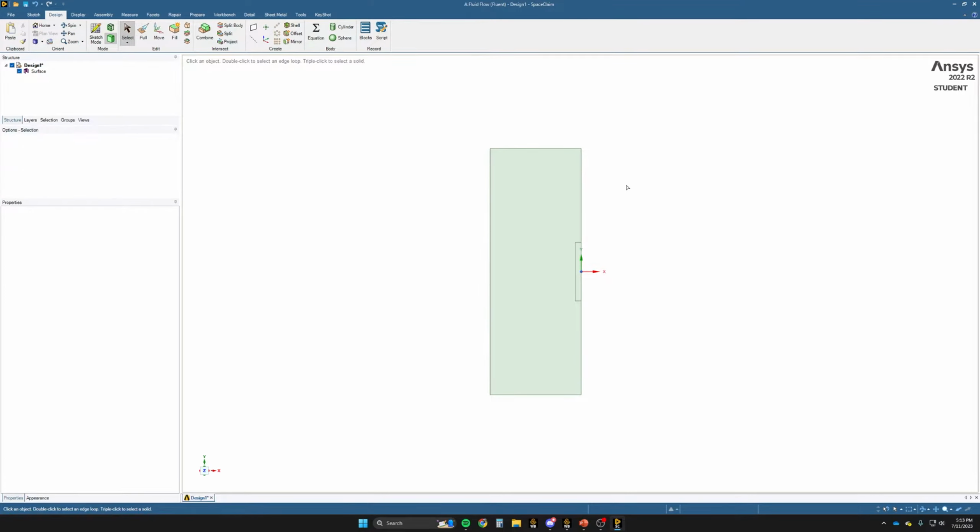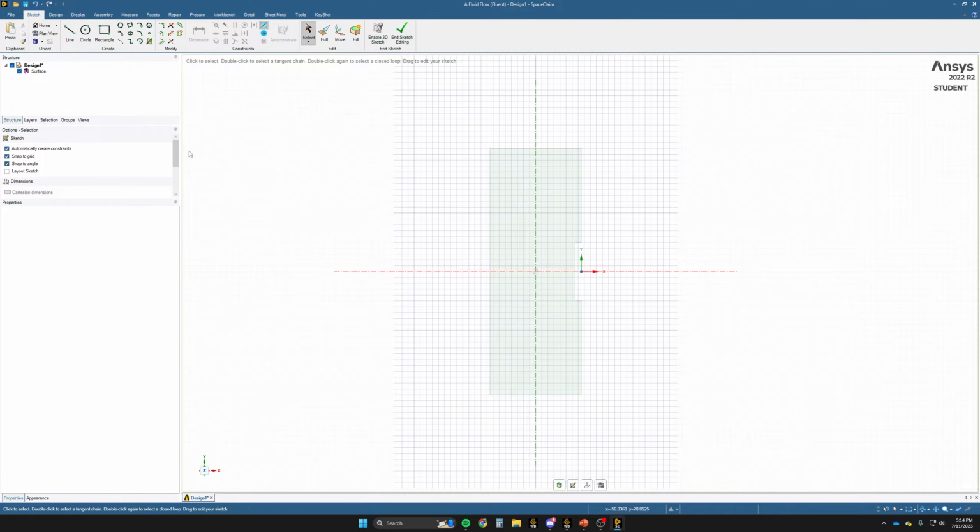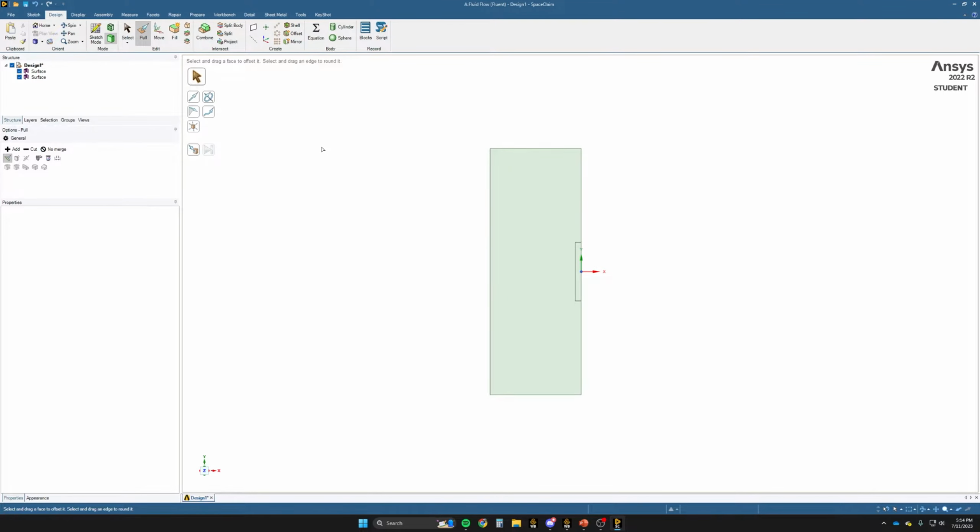The next thing we're going to want to do is split these two surfaces so we have two separate cell domains in our simulation. The easiest way that I found to do this is by simply deleting our inside face by just hitting the delete key on the keyboard, going back into sketch mode, and just redrawing that rectangle. And we can go ahead and end sketching. And now what we'll see over on the left here is that we have two surfaces, one for the air domain and one for our chip.